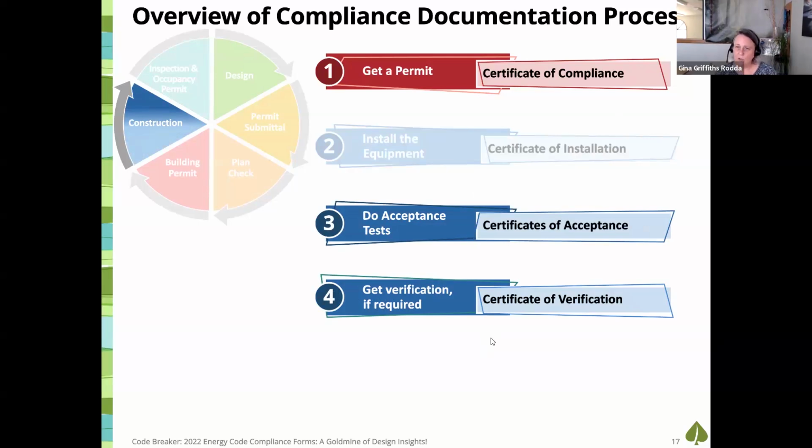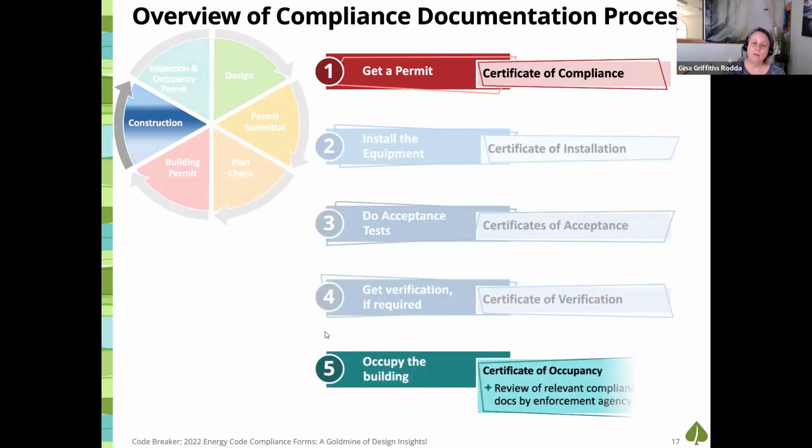This is not the contractor. This is someone who's not employed or related to the contractor that's going in and testing specific building features that are required to be tested by the energy code to confirm that the energy savings promised by the energy code is being supported with that project that's finally getting that certificate of occupancy and people are going to start moving in.